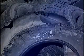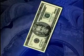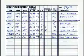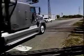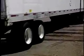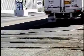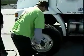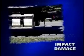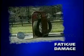Understanding the reasons why tires are being scrapped is important in the protection of your investment and in lowering your overall tire cost. You should know what caused each of your tires to be taken out of service. Operating conditions, avoidable or unavoidable, require an understanding of all potential causes and resulting effects on the tire and the tire budget. This video has reviewed some of the most common causes for tire removal. The conditions were categorized in the following areas: run flat, air infiltration, pinch shock, impact damage, and fatigue damage.